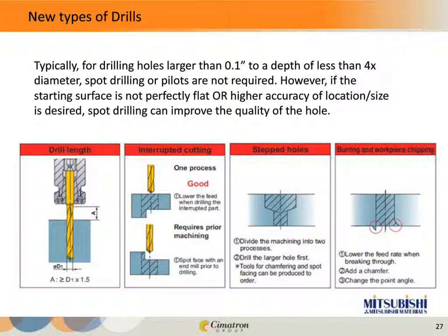The third illustration here shows a step tool. When I see this, I think about a counterbored water line, like in a mold application. I actually did run a boring mill for quite a few years in my early 20s. In a hole like this, I probably would have drilled the water line first and then threw a big high-speed steel drill in there and just chased that smaller diameter. Well, with carbide drills, we don't want to process it that way. We would want to process the large diameter first and then the small diameter second. So the order is very important when using these types of drills.